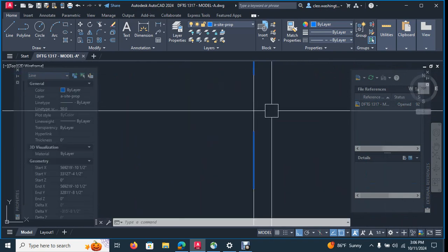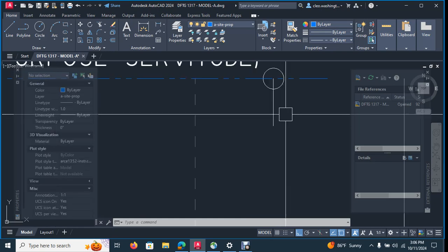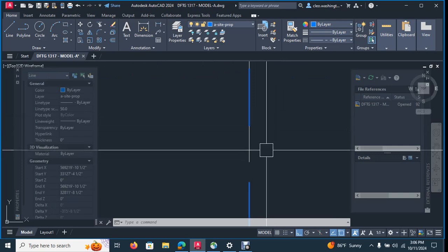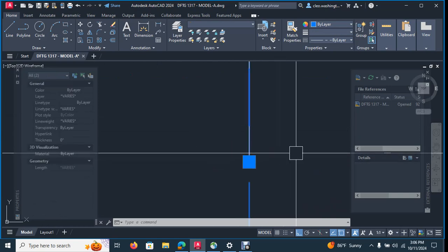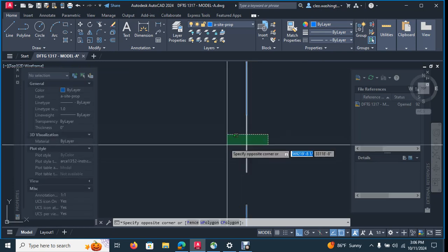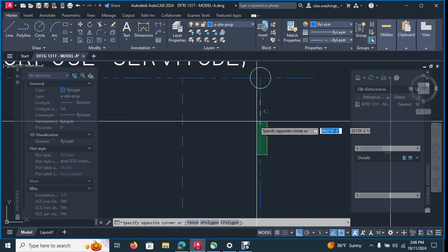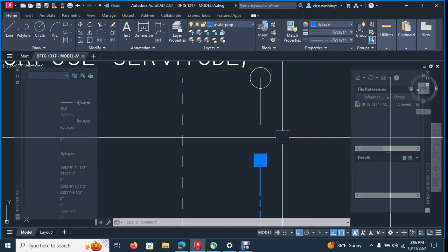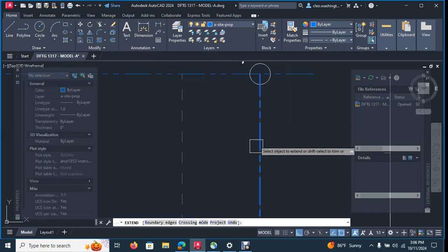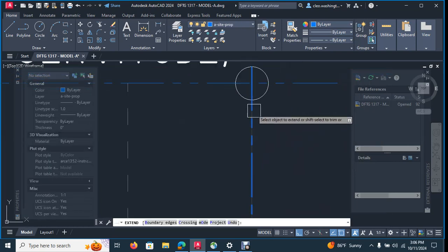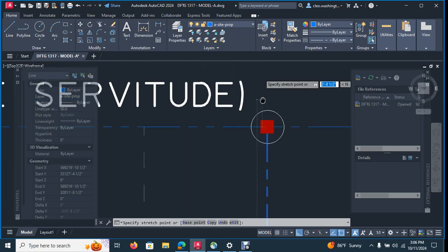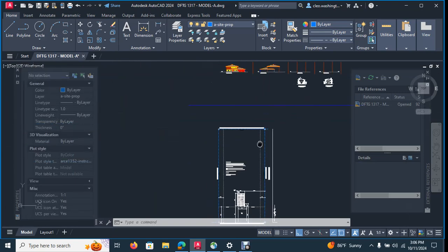And let's delete this underlying line, right? Not that one, but this white line. Let's delete it. Stubborn. Okay, in that case, let's take this line, drag it down, delete this line, and hit EX for extend, and click it back up. Okay. So that's how you do your boundary line.